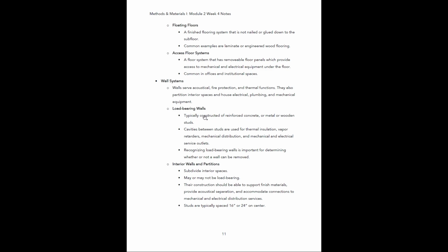Load-bearing walls are typically constructed of reinforced concrete, metal, or wooden studs. The cavities between the studs are used for thermal insulation, vapor retarders, mechanical distribution, and mechanical and electrical service outlets. All right. Recognizing load-bearing walls is important for determining whether or not a wall can be removed. I think last week we had a little video on how to recognize load-bearing walls.